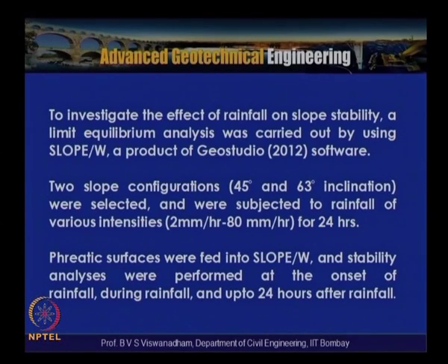The phreatic surfaces were fed into SLOPE/W, and the stability analysis was performed at the onset of rainfall, during rainfall, and up to 24 hours of the rainfall. So, the intention is to bring out the effect of rainfall intensity and its duration on the stability of a slope.